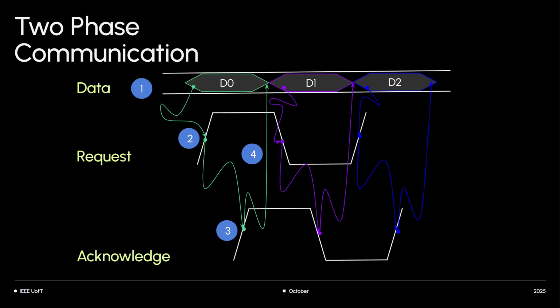When does the data packet number 3 happen? Number 3, yeah. So you've taken a data packet, you put it on a data line. That's number 1. And then once you put it on the data line, the sender is telling the receiver to clock it in.